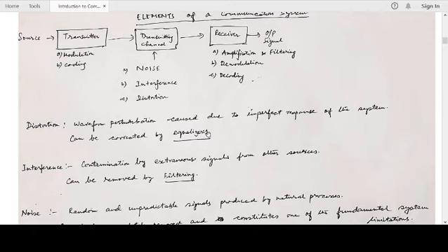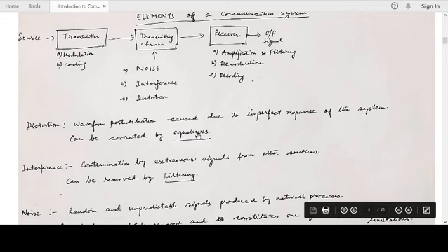This is typically corrected by something known as a channel equalizer at the receiver end. A channel equalizer can be implemented in analog mode, or, if possible, you can discretize the signal, go to the digital domain, and then you have the flexibility of implementing an adaptive equalizer, where you can adapt the various taps of the equalizer depending on the channel scenario. When the channel changes, you can correspondingly adapt the equalizer.